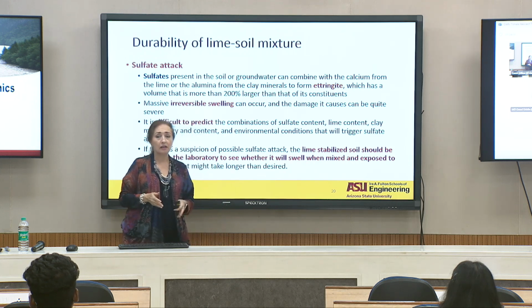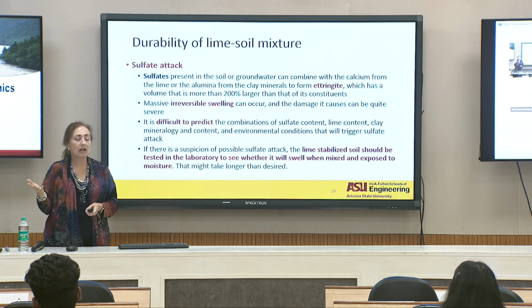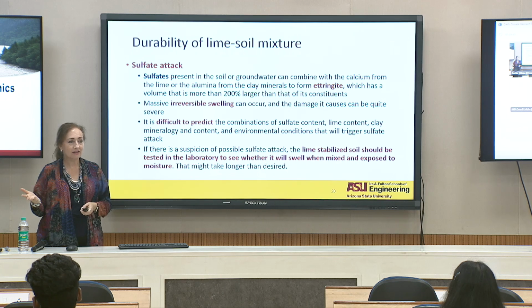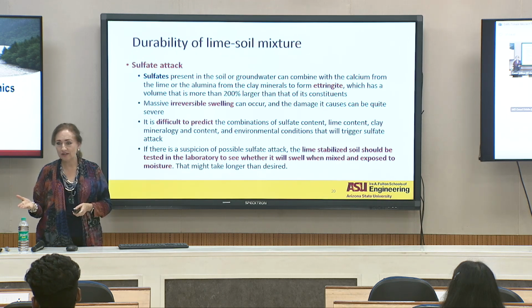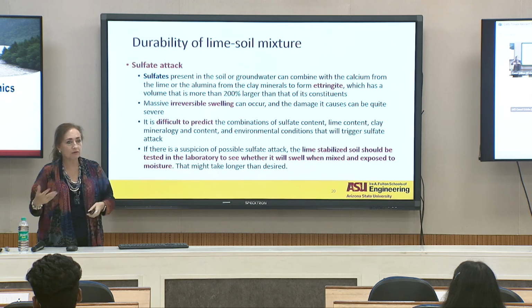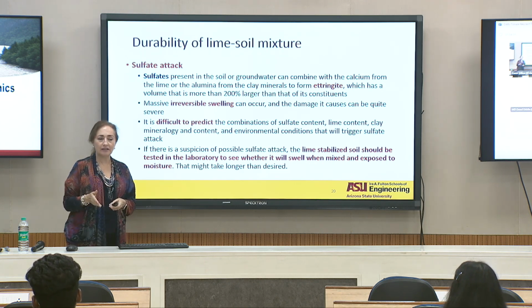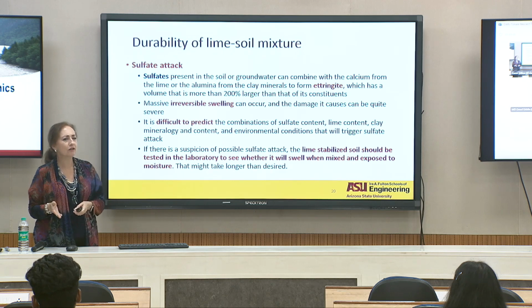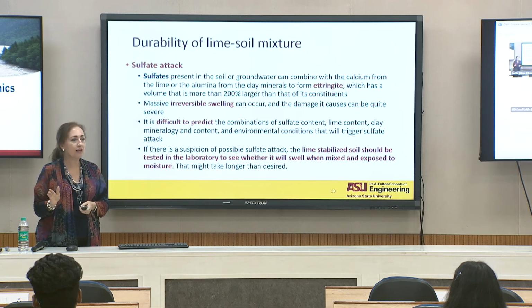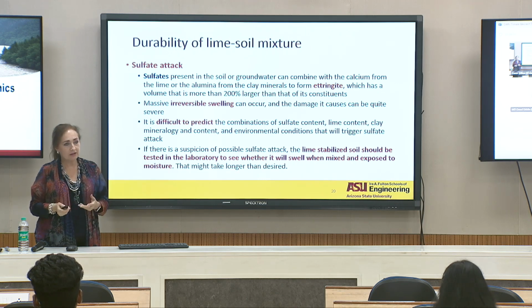So what happened here? The asphalt mix was okay, the formula was okay, the thicknesses were okay. They figured out the soil had a lot of sulfates, and they did not check for sulfates. The company went bankrupt, and obviously they had to pay back and redo all of this work. And the sulfate test at that time cost about $100. Nothing, right? So just a simple thing like that will bankrupt a company, your company. So you need to be very careful with this.